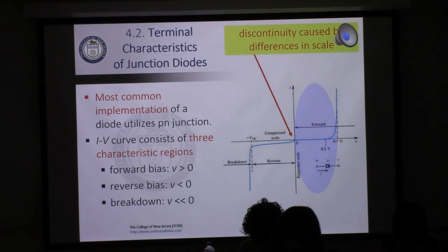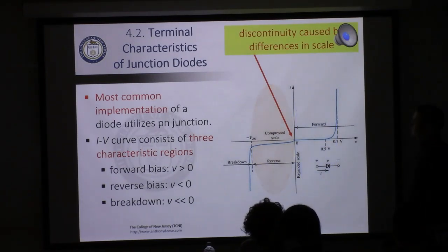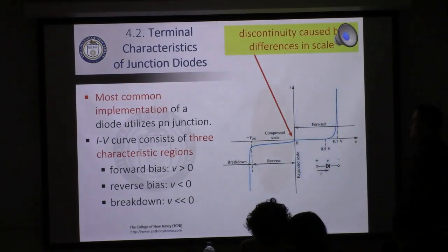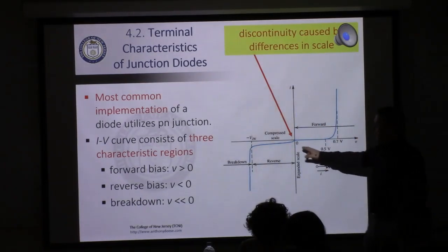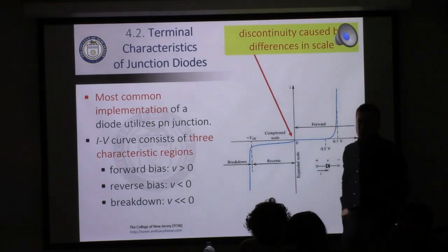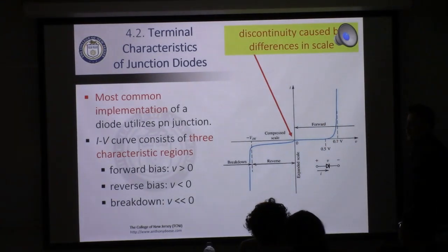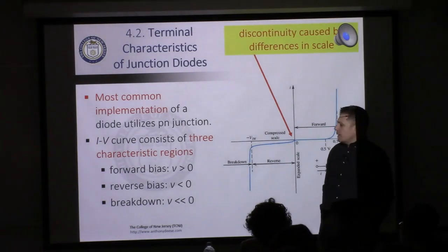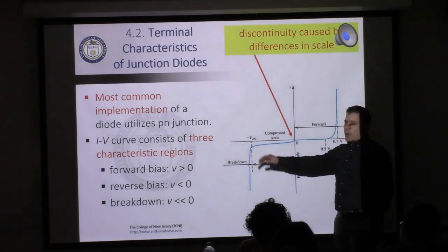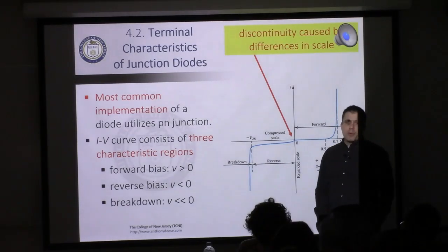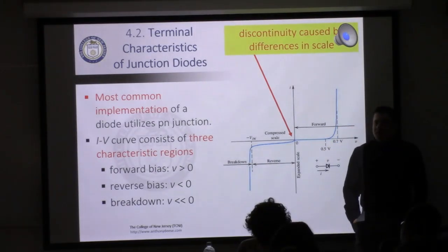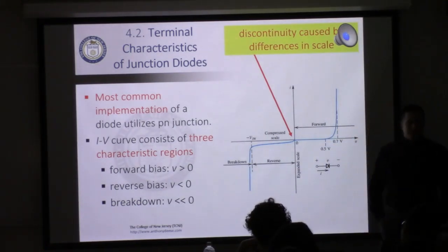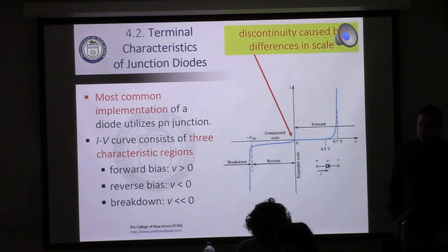Okay, so this is a little bit more of a detailed look at how the diode works. We haven't discussed the breakdown region yet. We didn't discuss that at all in Chapter 3. For better or for worse, we didn't really go into the physics and the science behind the breakdown region. But a diode is not going to block forever. There's going to be a point where the magnitude of the electric field that you're applying overcomes the barrier against it and current begins to flow.